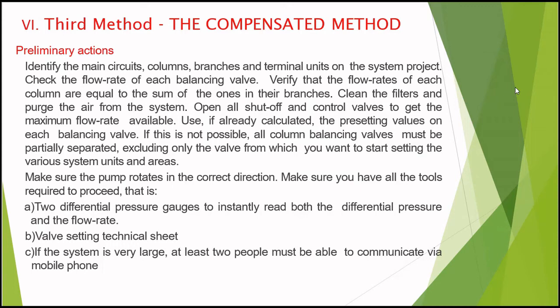You have to make sure that the pump rotates in the correct direction and make sure that we have all the tools required to proceed, which are two differential pressure gauges to instantly read both the differential pressure and the flow rate. And we also have the valve setting technical sheet. If the system is very large, at least two people must be able to communicate via mobile phone.